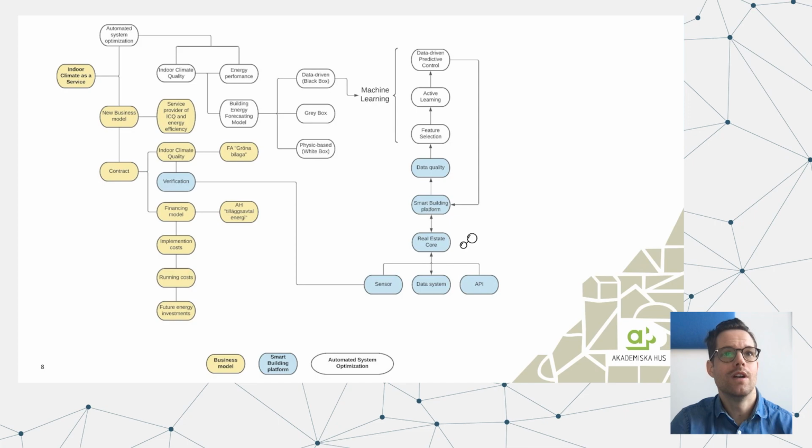The DPC is designed as a supervisory control strategy that provides set point recommendation to the building. Data-driven models built with large data sets often have overfitting issues and high computation cost. A systematic feature selection process that selects the features with the best model performance is implemented in this case study. Since most buildings are operated under very limited operation modes, weather conditions and control set points, the data-driven model trained using the data often has poor accuracy when forecasting unseen conditions. So, to generate more information, training data and active learning procedures are implemented in this project.